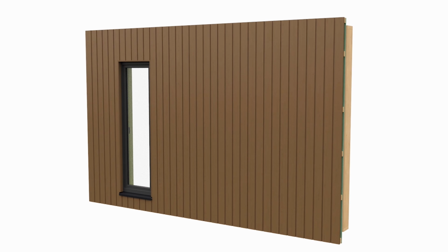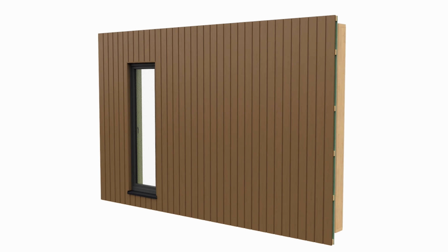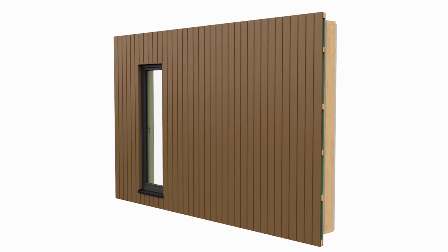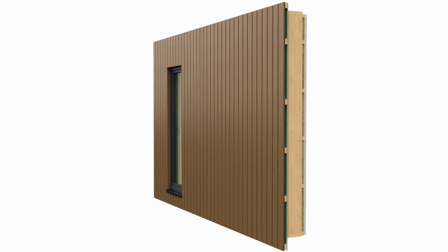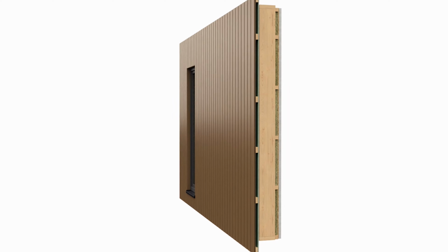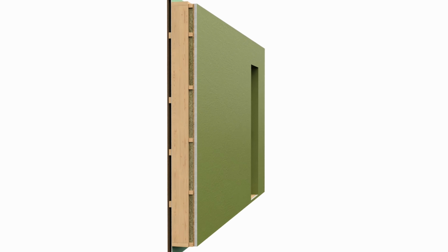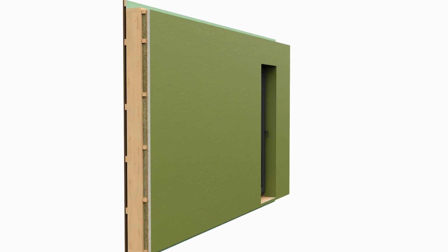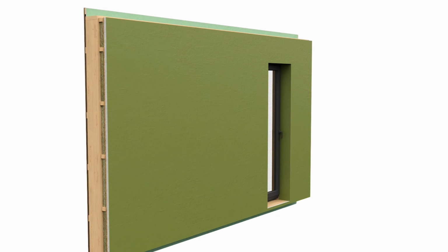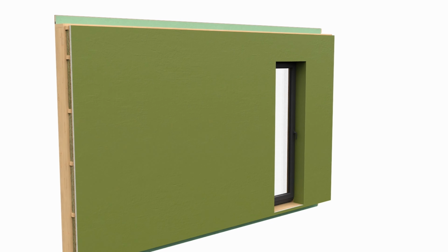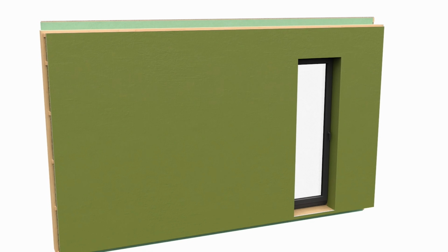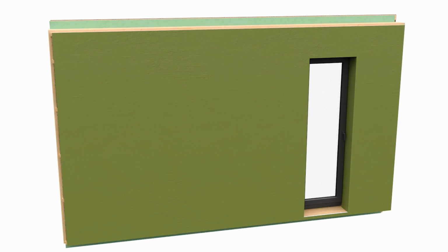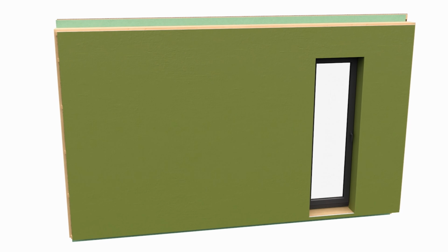The construction of the external wall depends on the type of building. Is it a kindergarten, private house, or apartment building? The technical solution is created by the engineers, which takes into account the requirements by the law and standard solutions developed by the specific house manufacturers. As a rule, the load-bearing frame of the external walls is significantly more massive than any other types of walls and may consist of several different partial structures attached to each other.